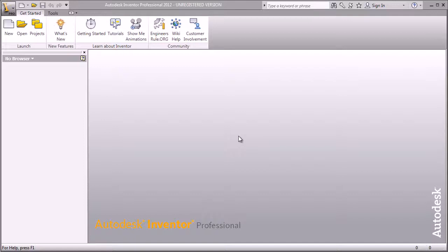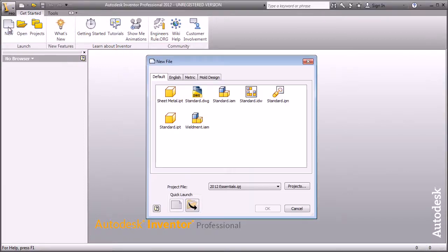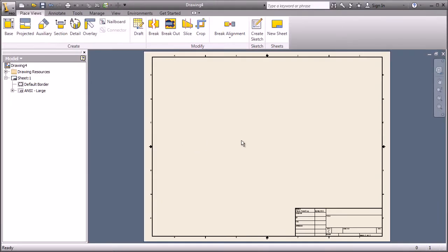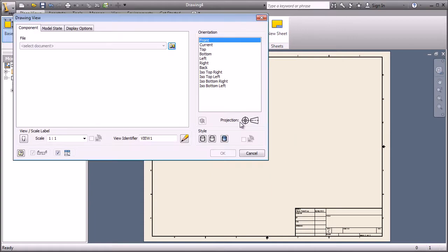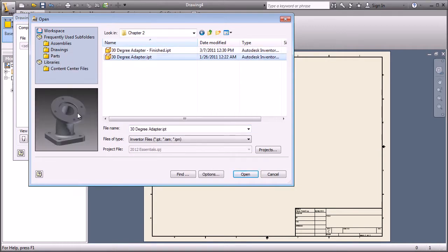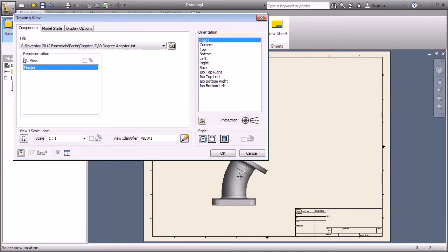Let's go ahead and make a few drawing views. Of course, creating 2D drawings from the 3D model is a much easier way of going than using a traditional 2D CAD system. We'll use our marking menu, where we can just gesture in the direction of the various tools. We can select any part we want. Of course, it will know if we have a part already open that we want to detail. Get a nice preview of the part in the open window so we're sure what we've got.